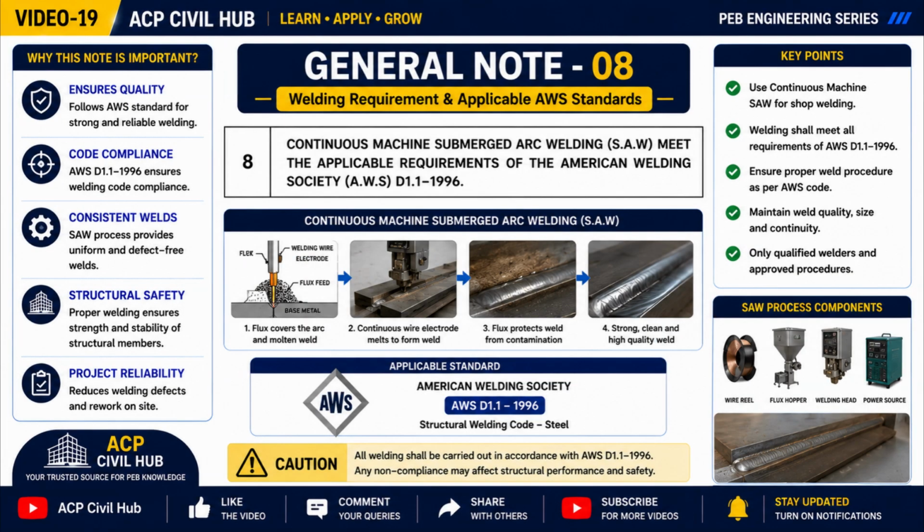General Note Number 8 specifies the welding standard to be followed during steel fabrication. It states that all continuous machine submerged arc welding, commonly known as SAW, shall comply with the requirements of the American Welding Society Standard AWS D1.1-1996. Submerged arc welding is widely used in PEB fabrication because it produces deep penetration, high-strength welds, and consistent quality.